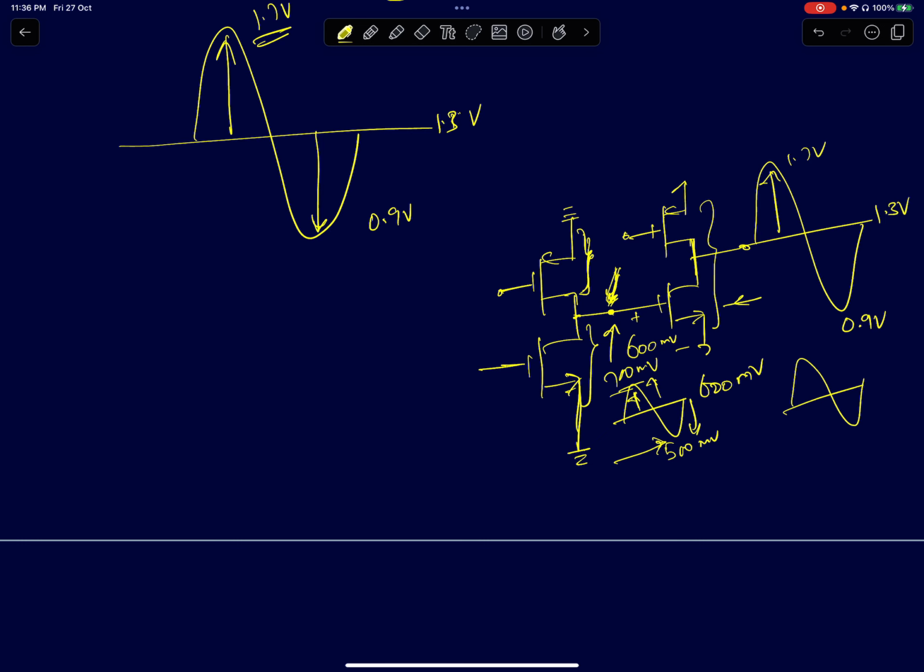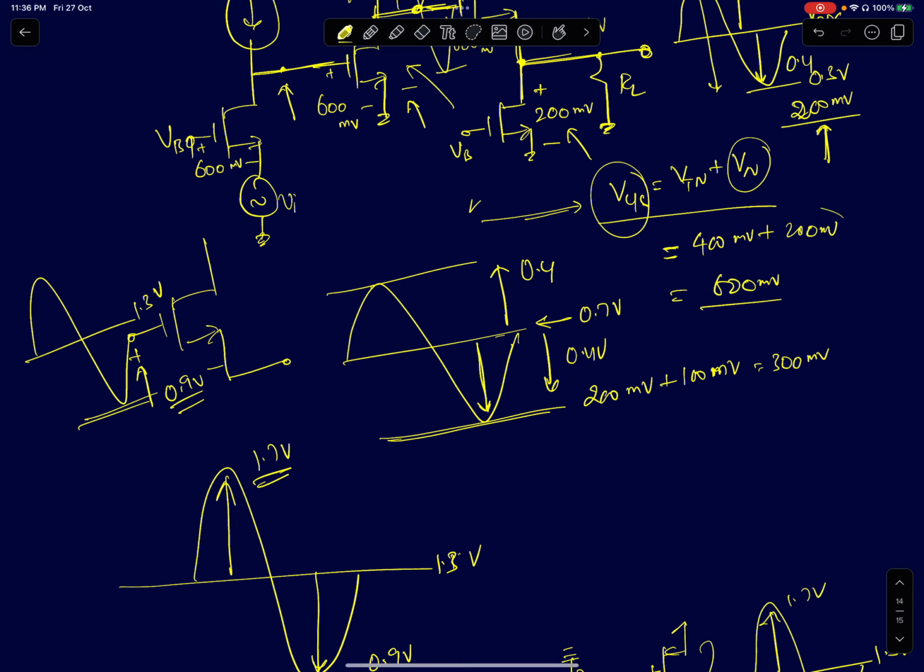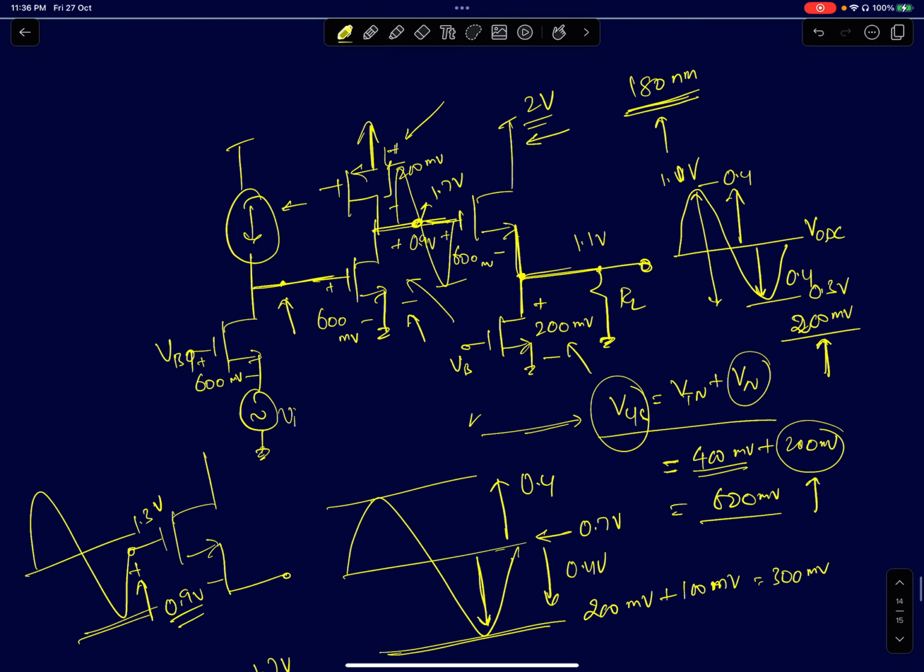So by choosing 200 millivolts of overdrive voltage, assuming a VT of 400 millivolts, you have to verify in your design what the VT is. I've just told you the procedure. You may have to alter this number by a few millivolts, tens of millivolts, if your VT is higher or so on. Okay, so that decides all the overdrive voltages. VGSs are all set. Now finally we are coming to the currents. What are the currents I am going to set for these devices?